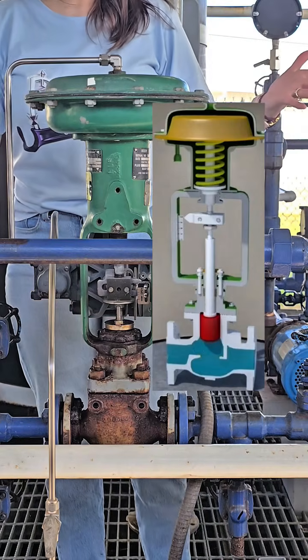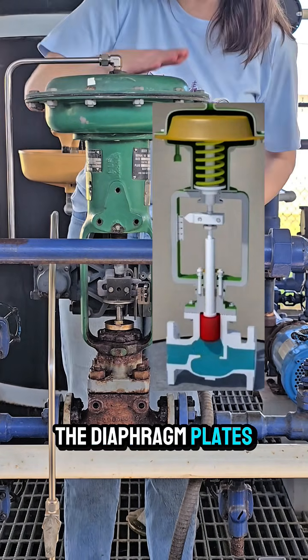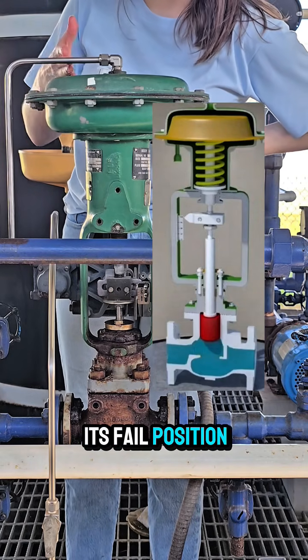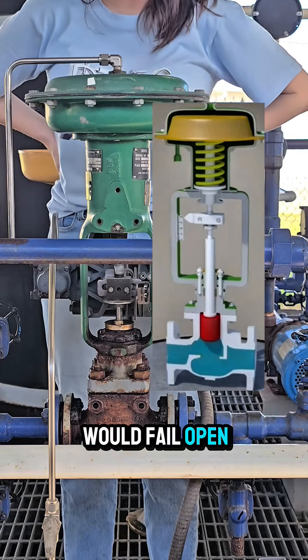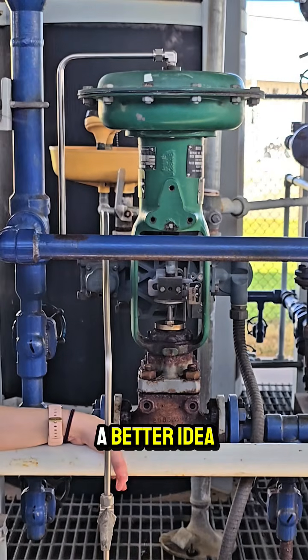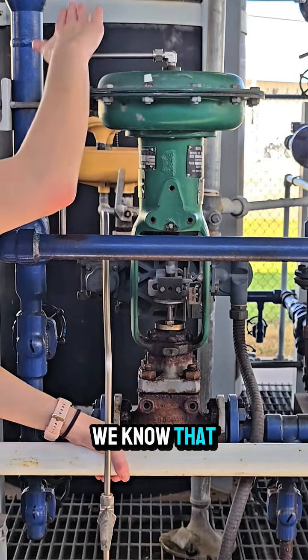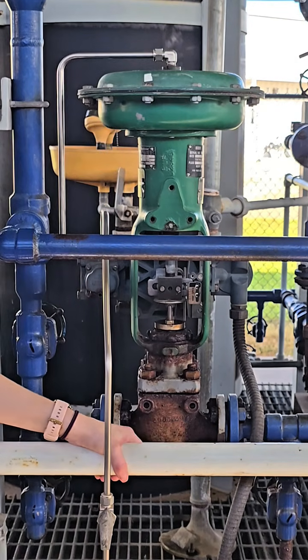So if we lose air, which means it fails, the diaphragm plate's going to push back up and the valve would end up in its fail position. Well, if this is up, plug is up, valve is open, so this valve would fail open. To give you a better idea of this, currently our valve is closed. We know that it's going to fail open because our instrument air goes into the top. So if I